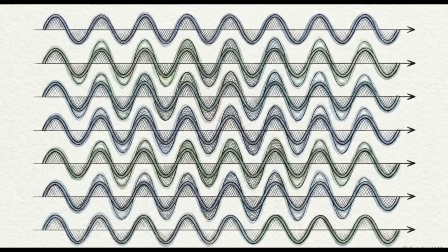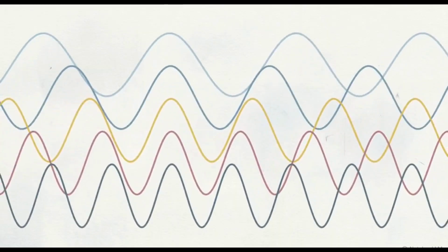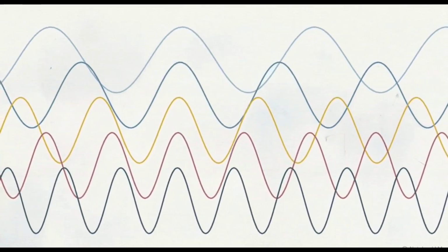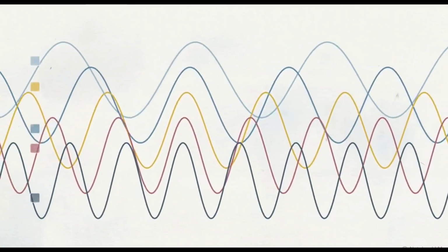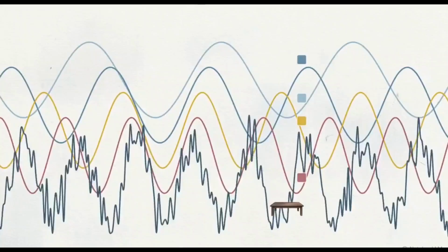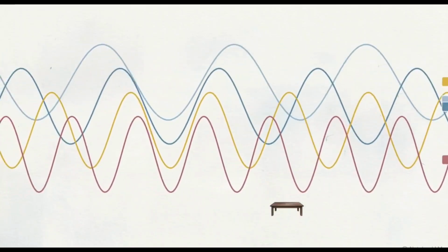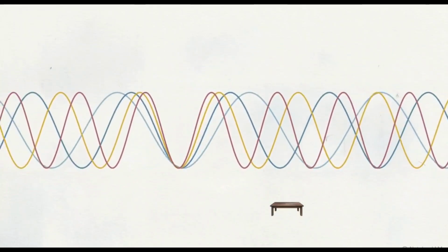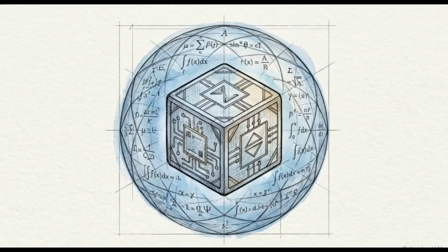To protect the data, modern Wi-Fi relies on a mathematical engineering breakthrough called orthogonal frequency division multiplexing, or OFDM. OFDM slices the data stream into multiple closely spaced subcarriers. Being orthogonal, they overlap tightly without colliding. Because packets are distributed, multipath fading isn't fatal. If one wave bounces off a coffee table and degrades, the stream survives. The rest carry right on through. OFDM provides the mathematical armor that allows fragile digital data to navigate the physical chaos of the open air.